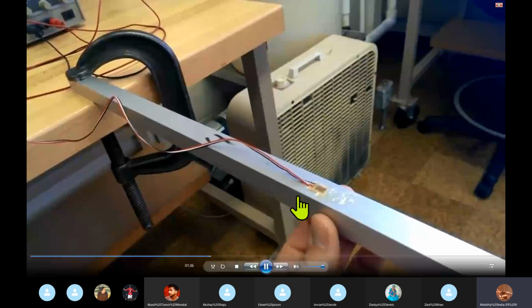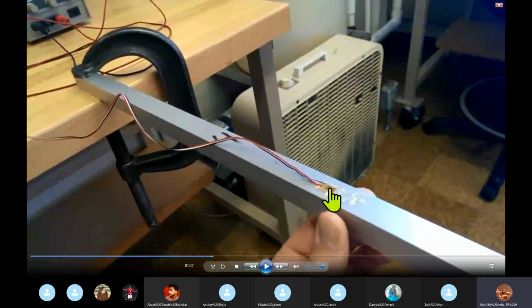See, this is the actual practical system. The wires are arranged in a zigzag pattern here. You can probably closely watch. It is like this, the wires are arranged. The 2 ends are here. In between, in this strain gauge, there is a lot of zigzag arrangement of the wires, and this is fixed rigidly onto this bar. This is attached using adhesive, firmly attached, so that the forces will act in this direction. You can see the video, it explains further.